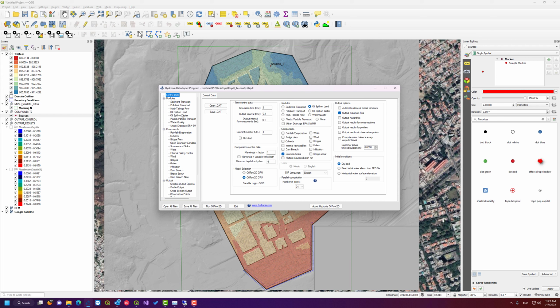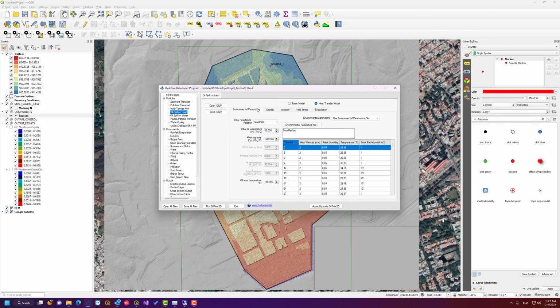model does not really simulate how different conditions would affect the oil. The oil temperature is pretty high usually when it comes out from the spill site, and then the ambient temperature will bring that temperature down typically, and oil behaves differently at different temperatures. The viscosity changes, the yield stress changes, and the oil can slow down significantly.